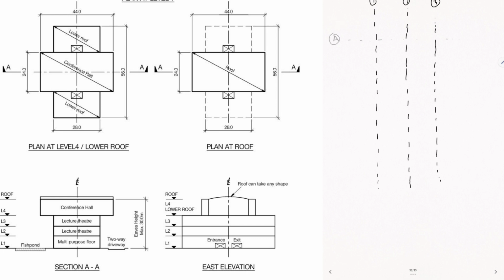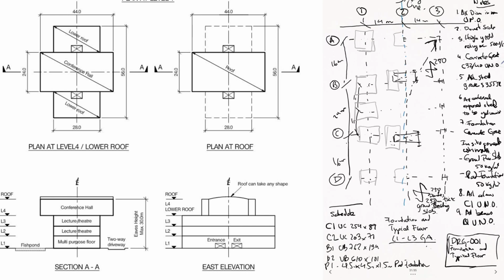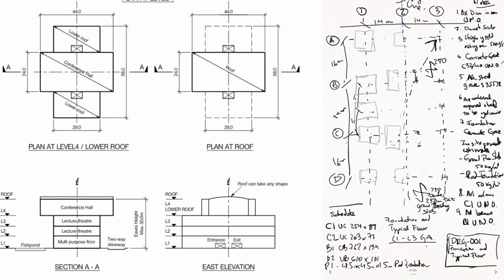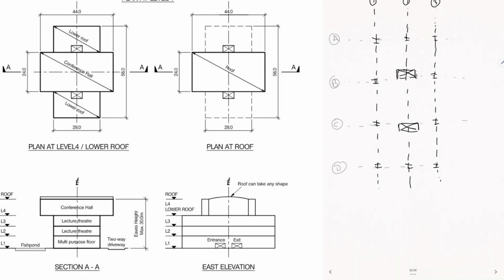Another very useful tip that I learned when I was practicing for the exam is do not start your next drawing until you have fully completed the last one. Of course, there might be times when you have to come back because you forgot something or you realize you made a mistake, but that's the thing. If you do not fully complete one drawing and then you go to the next one and you realize there's a mistake, you carry that mistake over to the next drawing. So make sure that you've fully completed all notes, all comments, all dimensions, etc.